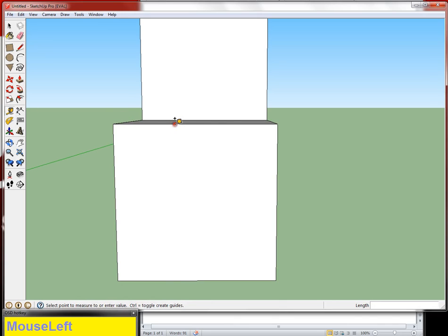One is to do the same thing we did up there with our tape measure tool and pull down 2 inch guidelines on each side. I want to be careful that from the top my pull line right there is blue, because that means I'm locked in the up and down direction. You can see here that I can also do it in green, and I'm going to go ahead and leave that guideline back there or up there so that I'm going to show you how that can be deceiving.